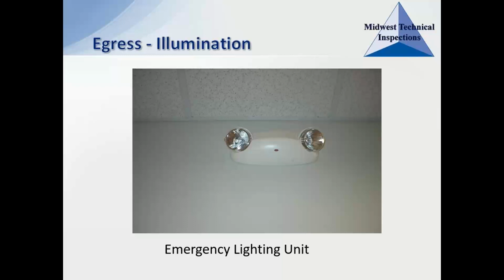Now, there are definitely some exceptions, for example, retail stores. They say that regardless of how late they're open, they don't need emergency lighting until they hit that 3,000 square foot mark. So those smaller retail stores aren't required to have emergency lighting, even though it would make sense from the best practice standpoint to have them. For most of our customers, the insurance companies, they are perfectly fine with us making recommendations based on best practice rather than on the NFPA Life Safety Code. The best practice is typically going to be stricter. It's going to require more protection than the bare minimum of the Life Safety Code.